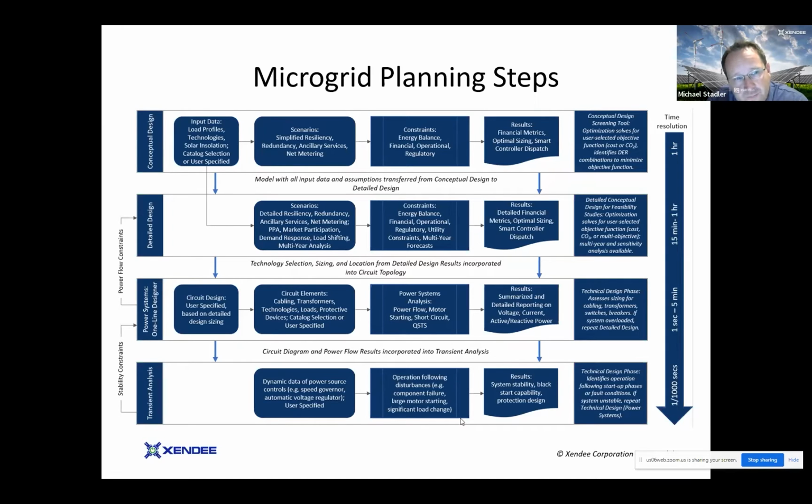So when you model or plan to build a microgrid, the first step in general is really to do this conceptual design. You want to figure out what technologies are attractive for your microgrid or project, what technologies you should consider, how much you might be saving here by installing this, how much utility costs you can save, or demand charges, whatever it is, or increase your resiliency. And typical data for this is really load profiles for a full year on an hourly basis, combined with utility information, tariff information, some technology information. Then as a result, you would get out technologies and the savings, as we mentioned.